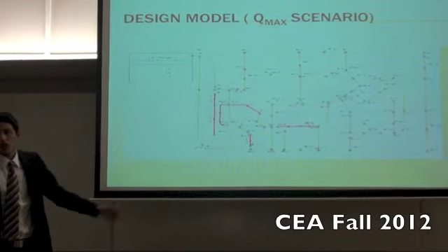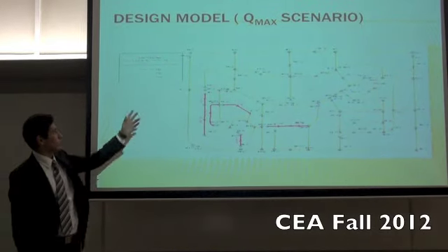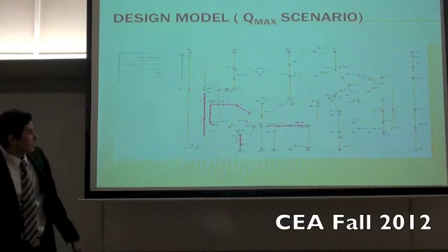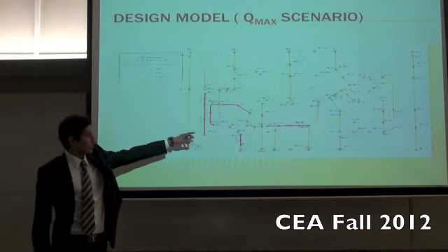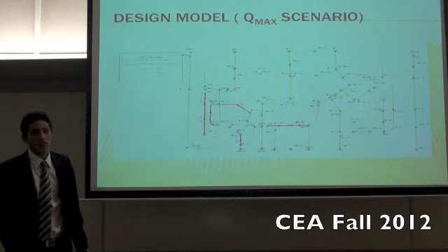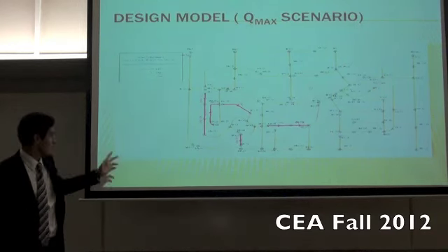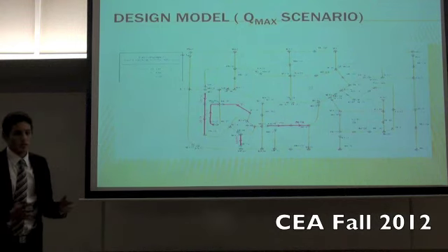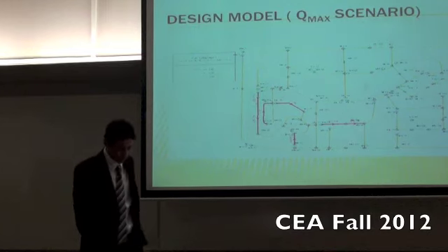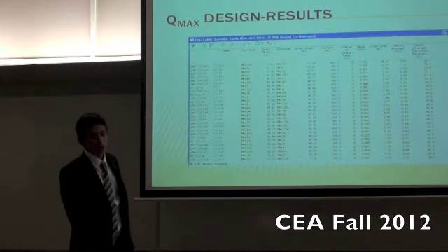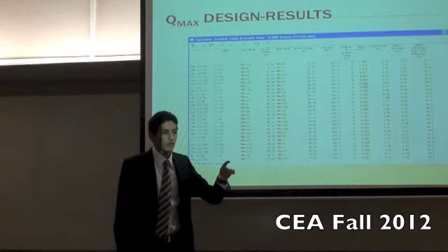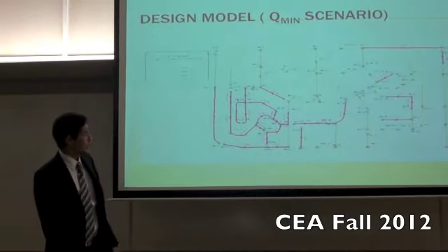The results show that the velocities are within our range of 0.45 to 3 meters per second, and only the start sewers had issues with velocities, which were less than 0.45. That makes sense because we still haven't collected as much discharge as the other sewers. These are the results obtained from CAD. The last one shows the percentage full of pipe in the sewer.